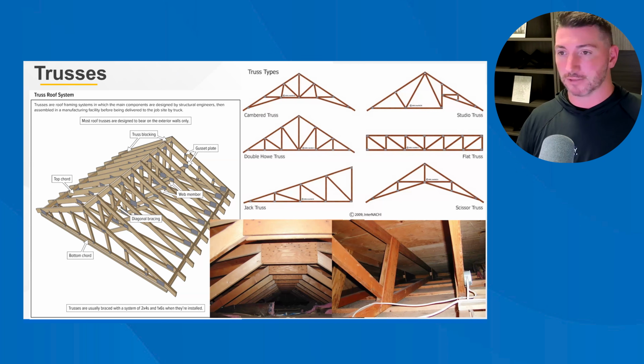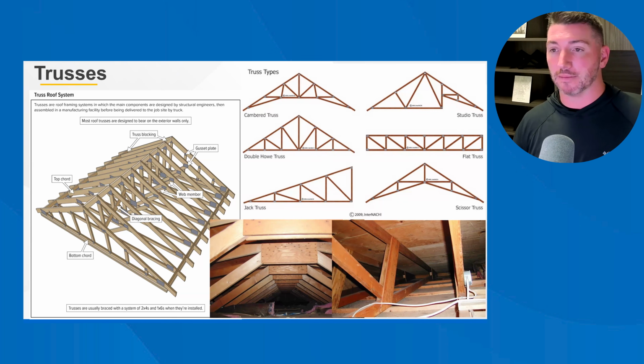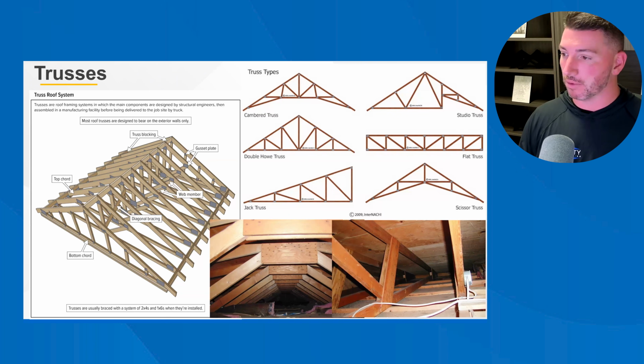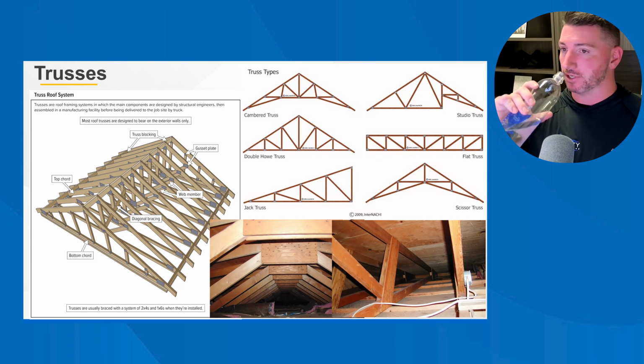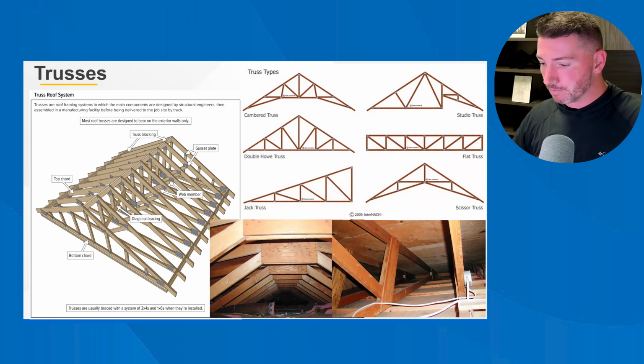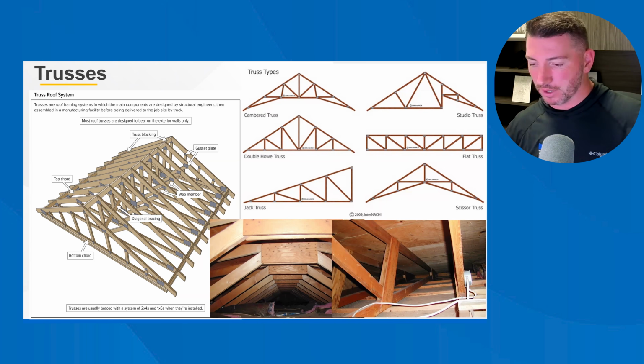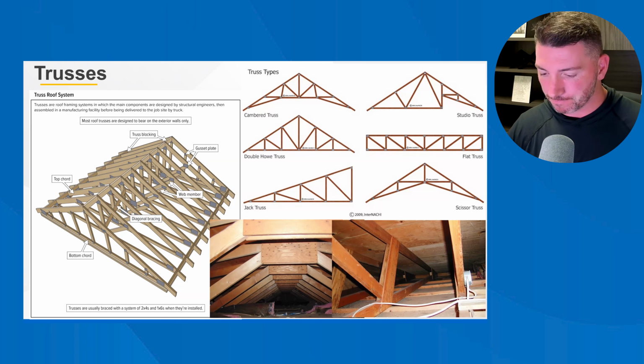And so it's just kind of this age-old thing that the guy comes in after the fact, whether it's the electrician or the plumber, he makes modifications to framing members to make his job easy without realizing that he's putting everything at risk because, hopefully, he just doesn't know what that compromise is that he's making by modifying those members. You cannot make any modification to a truss system without a sign-off by a licensed professional engineer. So they're engineered framing components. They're usually manufactured in some kind of a plant.